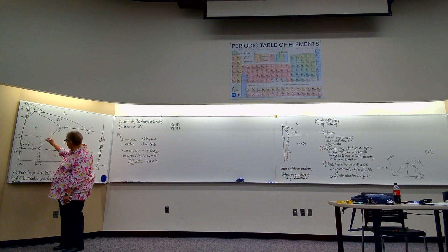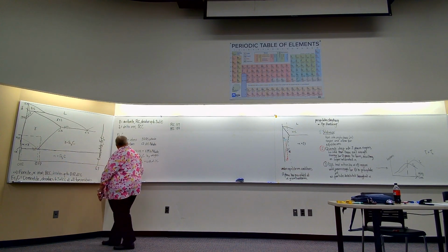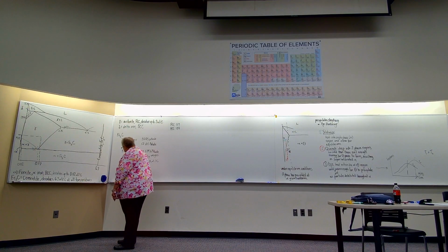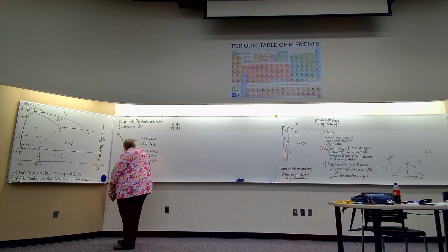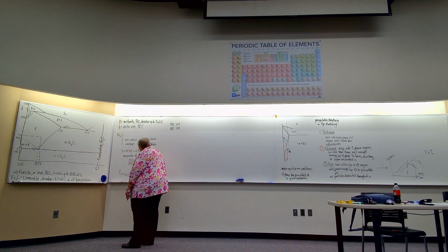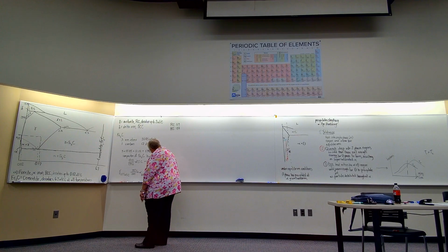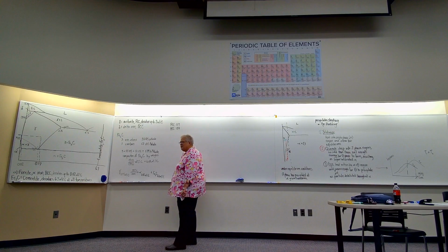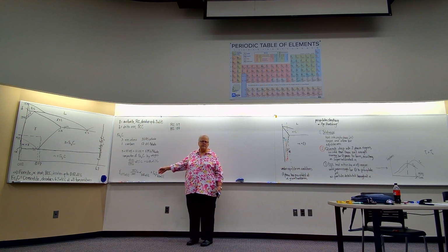So what do I have here? I have gamma at 0.77 weight % carbon, and when it's cooled through 727 degrees C, it transforms to alpha iron with 0.02 weight % carbon plus cementite with 6.7 carbon. What did I just write? What is that? Transformation.